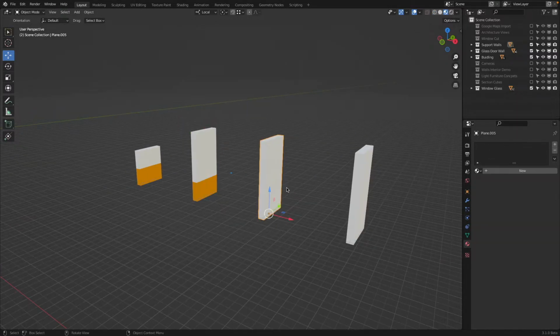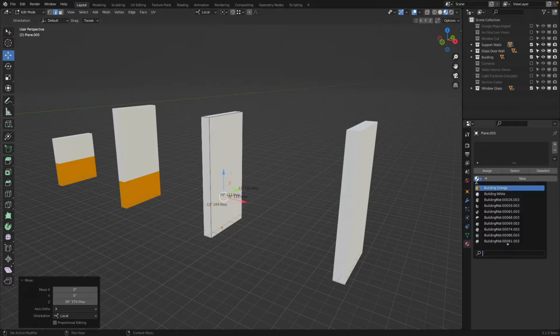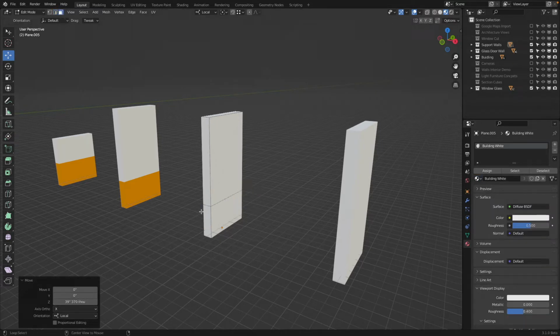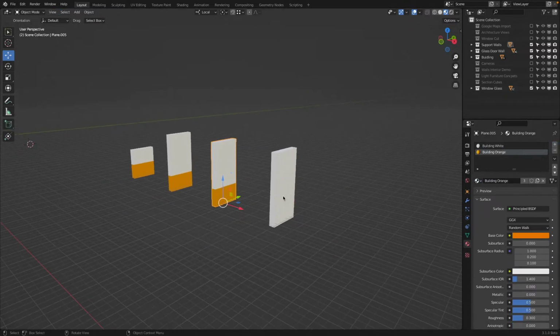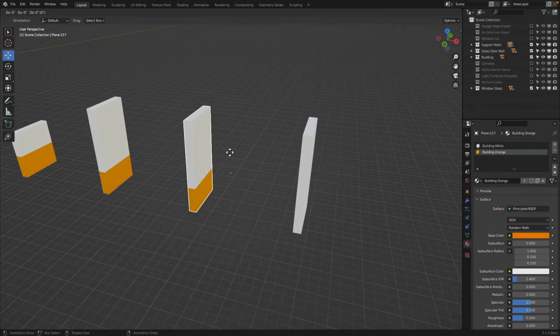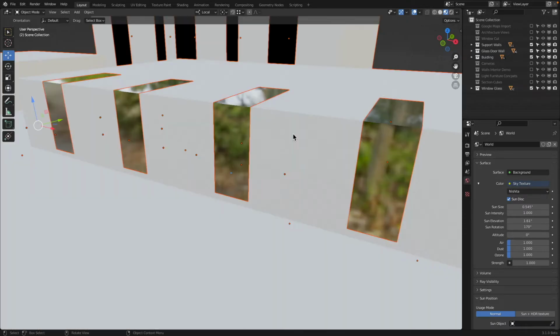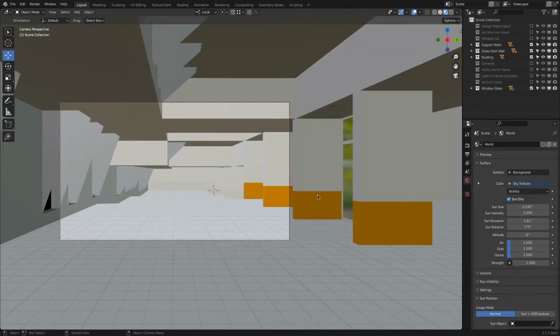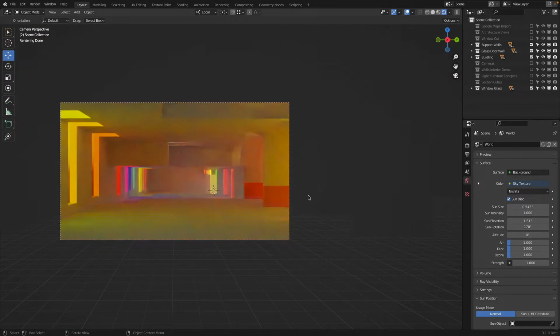There, cool. Go to here, edit mode, Control R, down, move this up 1 meter, alt click on this edge, makes the loop. They're not the same. Well, that could easily be the same, to be honest. Alt D and X, snap, H, click this one, X and delete, Alt H, and a 0 there. Cool, now if we do a rendering, there you can see how we have this material nicely always at this 1 meter line.